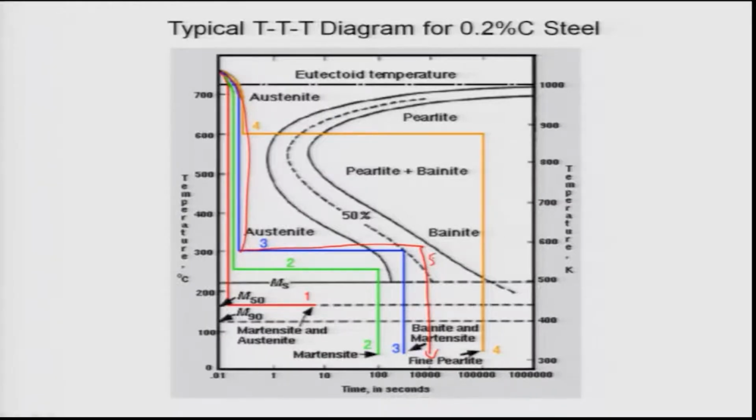And now you can actually make different kinds of bainite. You can cool it and do that, this will lead to upper bainite, or you can cool it, keep it there and quench to water, giving upper bainite plus martensite, and 3 or 5 will lead to lower bainite plus martensite. The different kinds of morphology can be built into the microstructure. And the 4 which is shown here leads to pearlite, obviously, because you are cooling it down and keeping it at a high temperature, 600 degrees Celsius, for a long time.